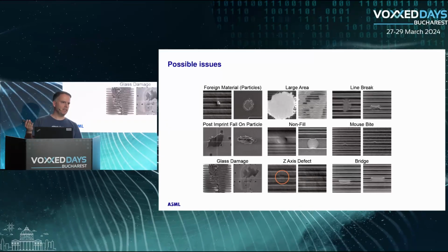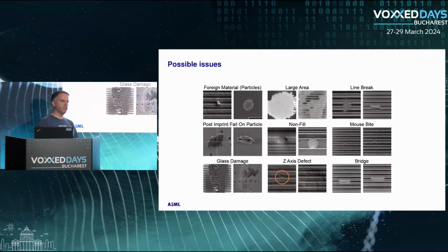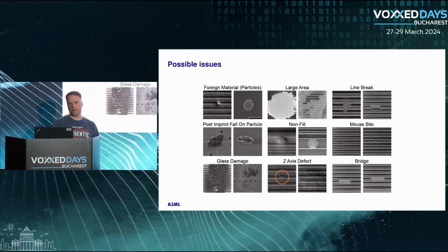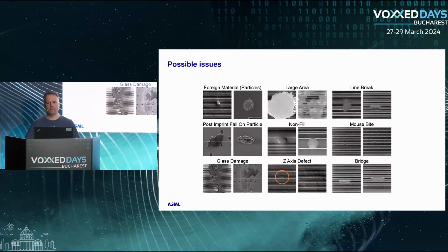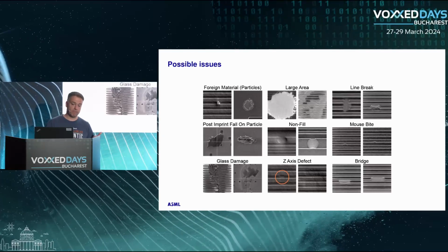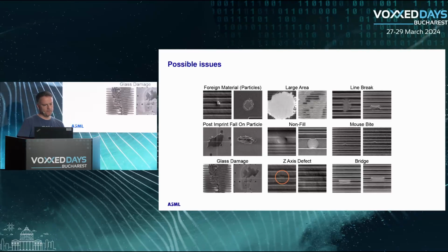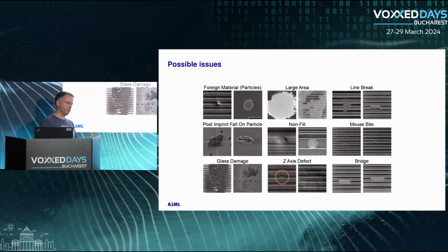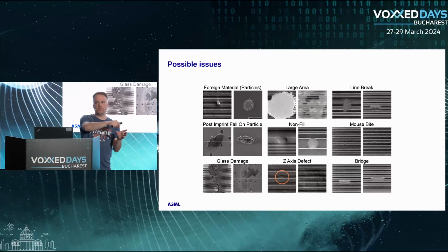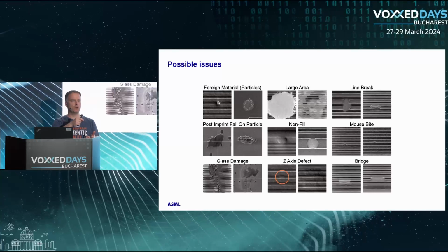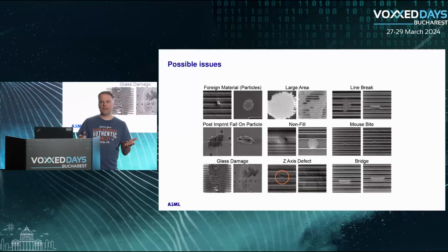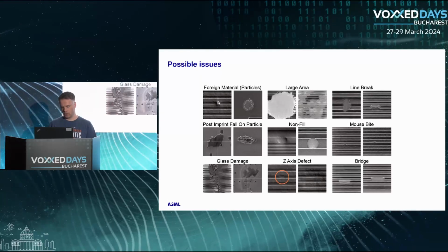So in the past, you also had these Celeron processors from Intel. They also disabled some of the cores of a normal Pentium processor and then sold them a bit cheaper. Of course, still our customers want to have those as few as possible. They want to have the good chips, and they try to prevent things like this. And you have sort of 2 approaches there that can go wrong. One is if there is a dust particle on top of the wafer, then maybe one chip is incorrect. But if that same dust particle is on the reticle, then each wafer that goes through is basically affected by that dust particle. So it's way worse.